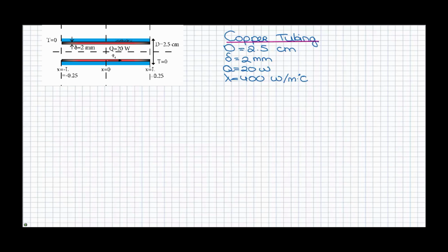Okay, we're now going to set up the energy balance of the small part, which is the same as the heat flux in, so at point x, minus the heat flux out, which is at point x plus dx, plus the heat production in the small part. You have to divide the heat production by 2 times the length, because then you have the heat production per meter, and that's what you want, because you have to multiply it by dx, which is the small part you're observing. Of course, the energy balance equals 0 because the situation is stationary.